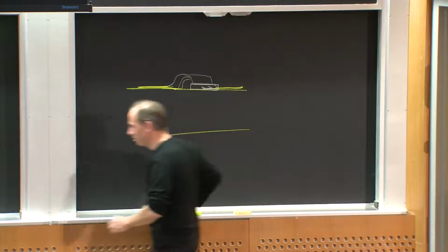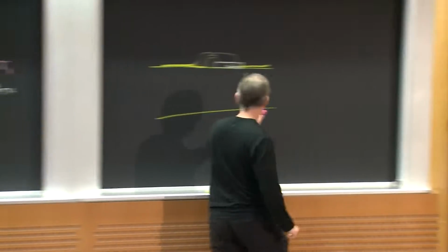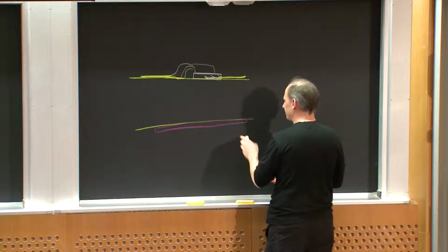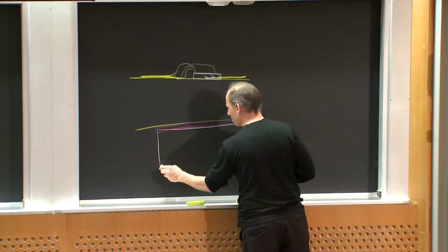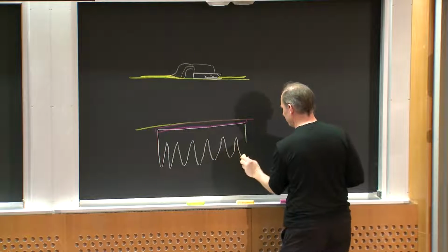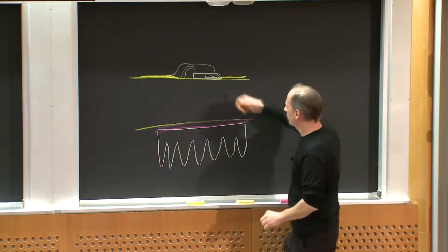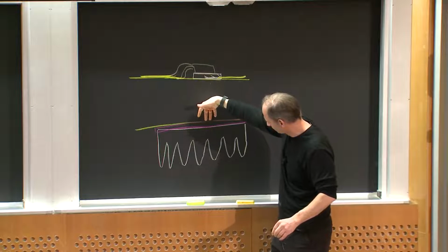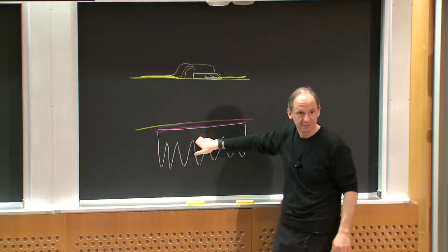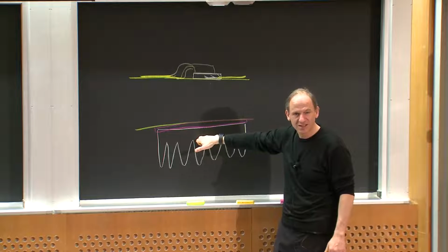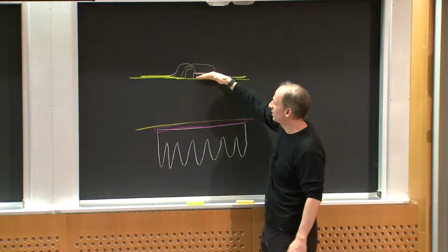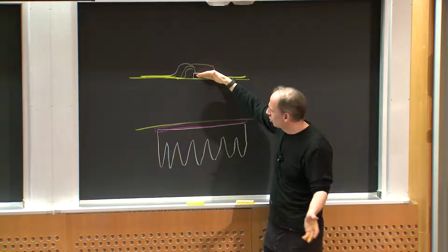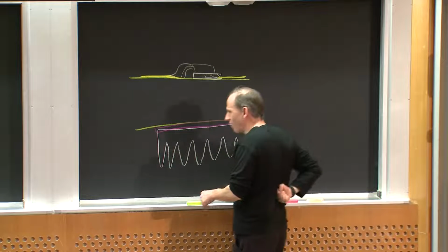So maybe on the other side of the board, I would put a thermal interface pad, right? And then a heatsink. The heatsink's mounted to the other side of the board. Okay? And I'm going to try to get heat out of the device, through the package, through the board, through the interface material, into the heatsink. And this is necessary because you want to connect the device to the board for the electrical connection, which is the most important thing. Okay?